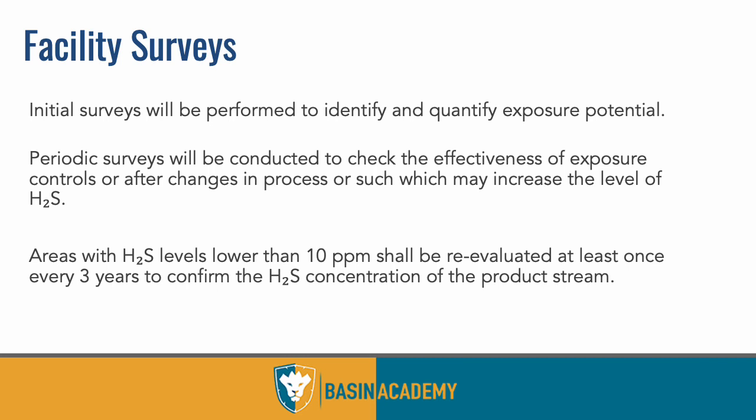If you see a sign that says danger or warning, H₂S may be present, that's essentially true, because H₂S can be everywhere. Some companies like to put these on every well, right? So keep that in mind. But once you see a breathing air system or a windsock that's red and white, then typically we know that there's H₂S, and when there's a red and white windsock, it's over 100 parts. Not every company does that, but if you see that, then that's what that means.